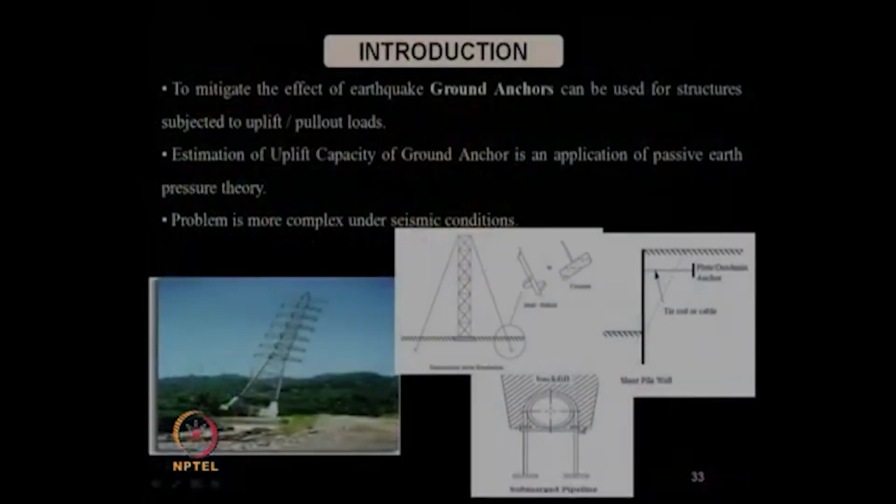Nobody would like to see, suppose, a wastewater line going underground, if proper anchoring systems, ground anchors, are not provided, and the uplift pressure at some point is more than the surcharge pressure at the depth at which the pipeline has been constructed, it can come out, right. So, to maintain the stability of the entire system, these ground anchors are very, very important.